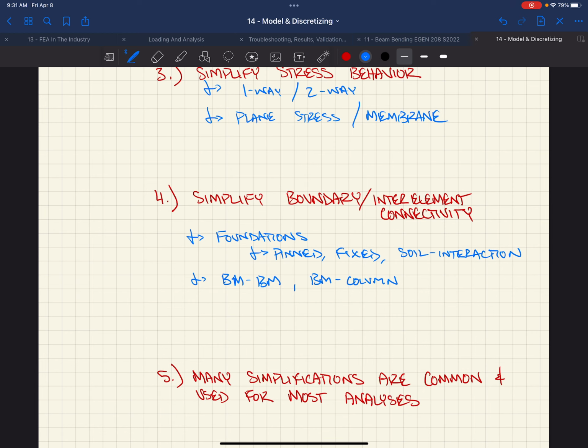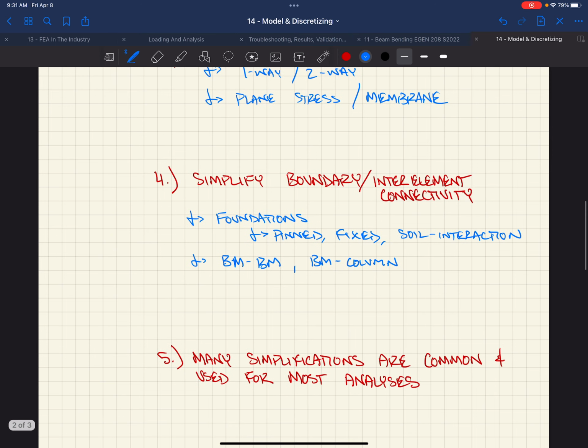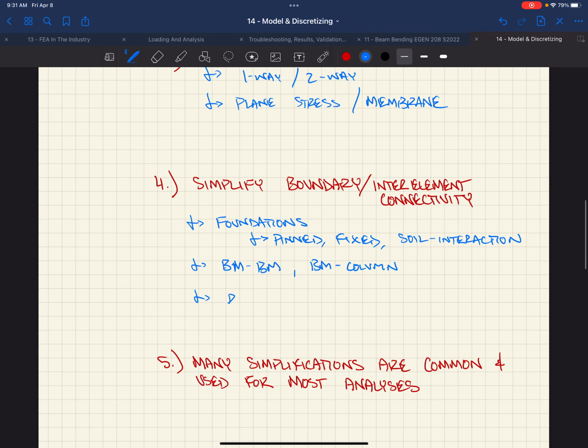You would maybe want to make some simplifications for our boundary conditions, maybe put a torsional spring in there instead of actually fixing our members together, because it's not gonna have its absolute stiffness. We make some other ones for what we're doing on our diaphragm.